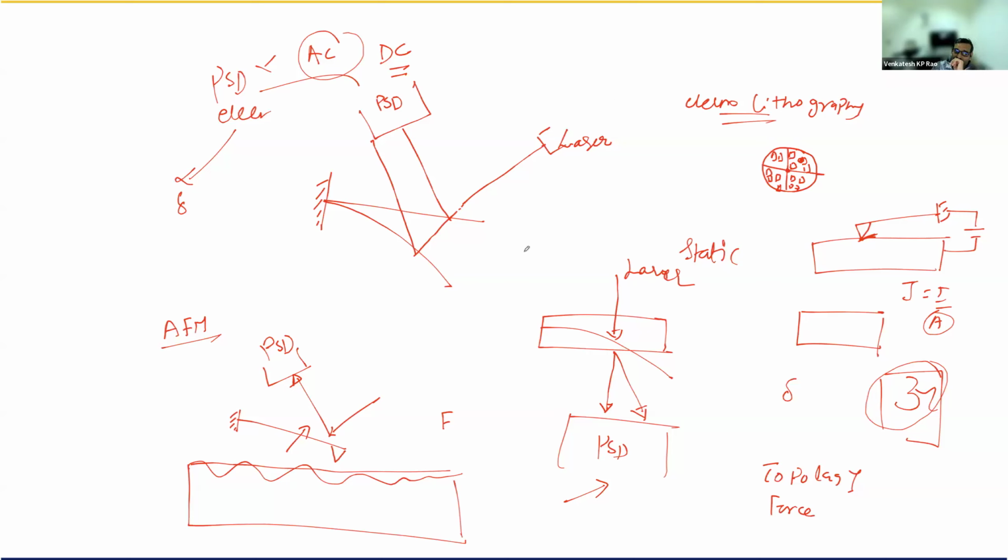Now it is not just the atomic force microscopy on this. There are plenty of other characterization techniques like acoustic microscopy, wherein, even if you have packaged devices, we can measure without even opening the device, just like how when the ultrasound passes over our body, it gives us all the images, right? The scanning acoustic microscope can even tell us the elastic moduli of each individual part within the complete assembly. You can extract it out with the help of a scanning acoustic microscope. That is what he basically calls a SAM, right?